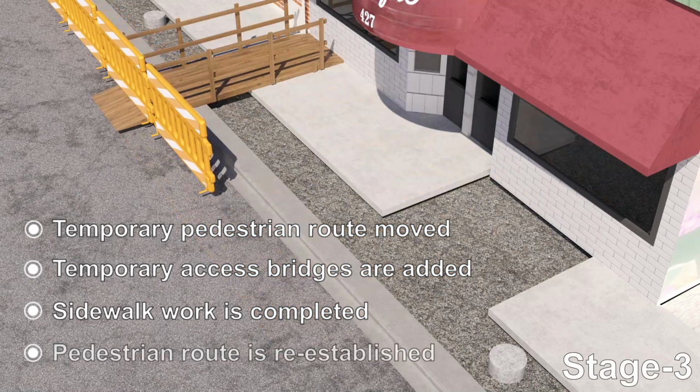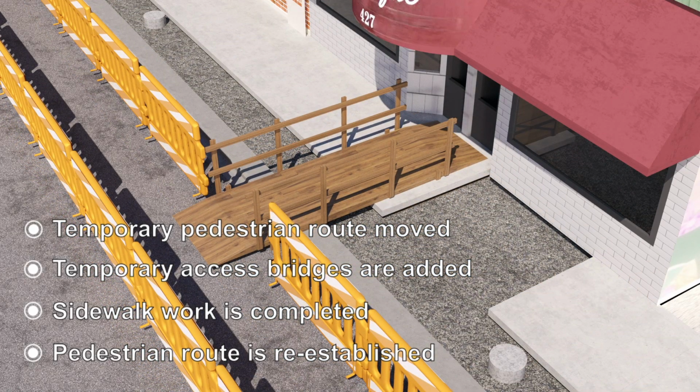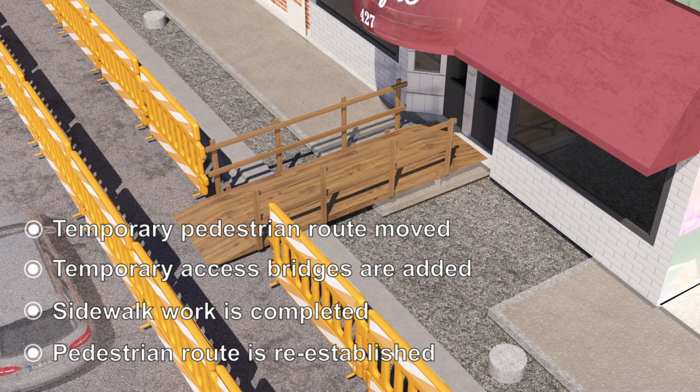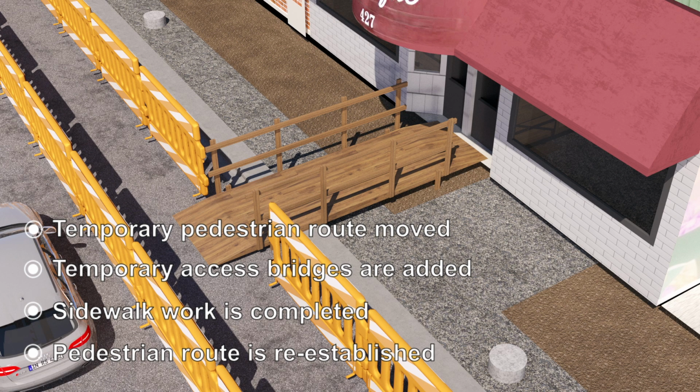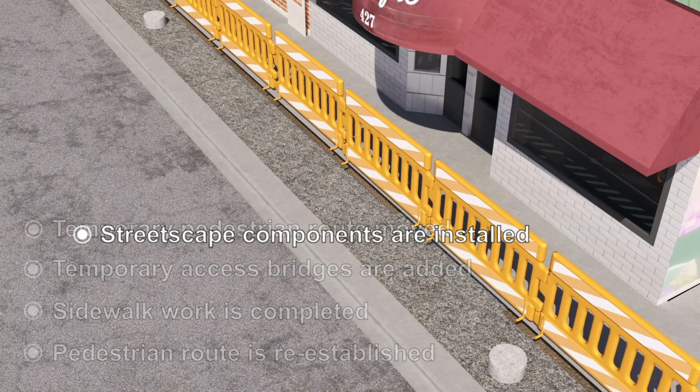Stage 3. In order to construct the parkway, a temporary pedestrian route is provided within the parking lane. Temporary access is also provided to the buildings through multiple wood bridges and ramps. The sidewalk along the building is removed. New sidewalk is then installed. The barricades shift and pedestrians are again routed along the face of the buildings.